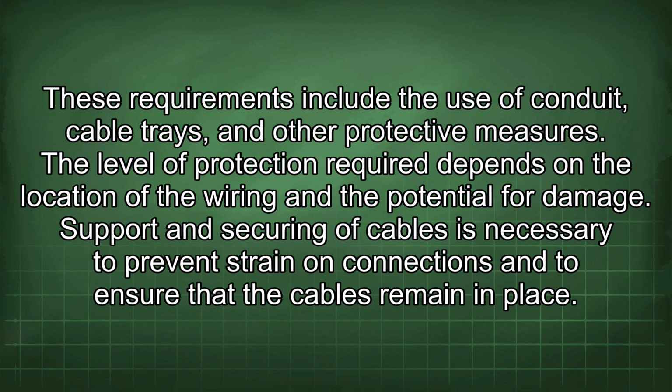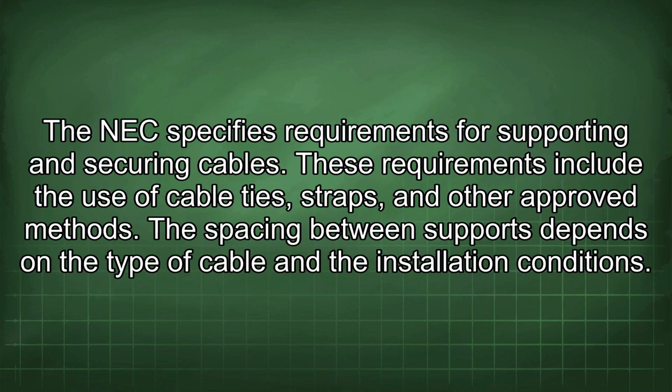Support and securing of cables is necessary to prevent strain on connections and to ensure that the cables remain in place. The NEC specifies requirements for supporting and securing cables. These requirements include the use of cable ties, straps, and other approved methods. The spacing between supports depends on the type of cable and the installation conditions.